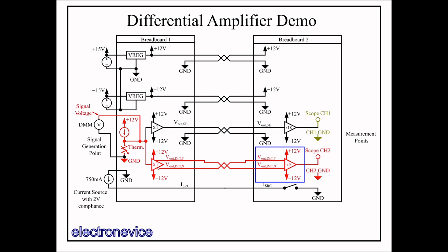Since the conversion from single-ended to differential effectively introduced a gain of 2 into the chain, the resulting signal level on scope channel 2 is the same as the single-ended result on scope channel 1. So if there is no interference, those two channels should be identical.